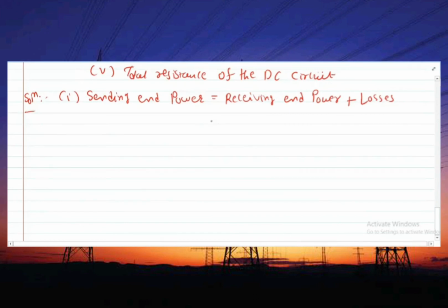You know the receiving end power is 1000 megawatt and the losses are 50 megawatt. So you can calculate that the sending end power is 1050 megawatt.